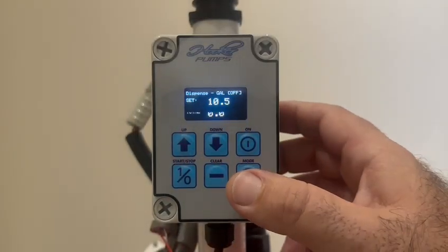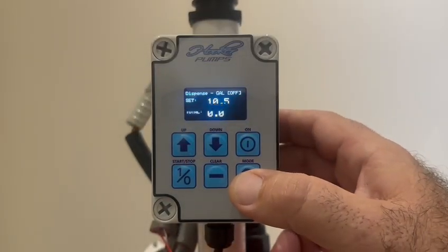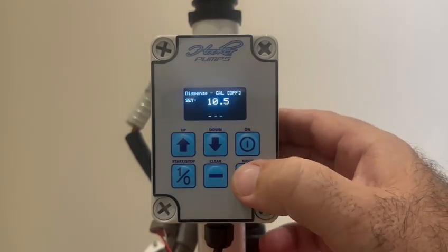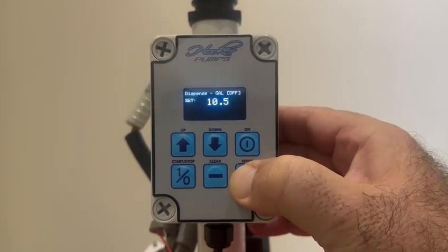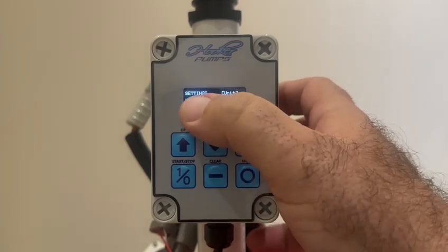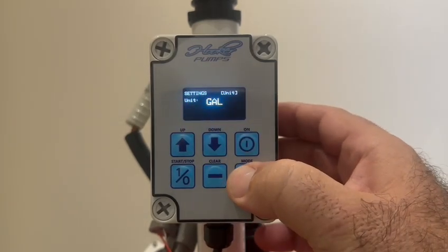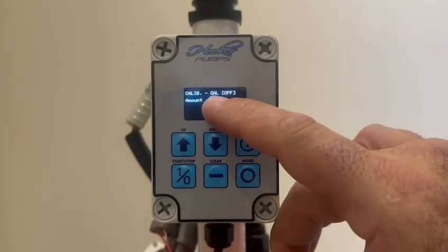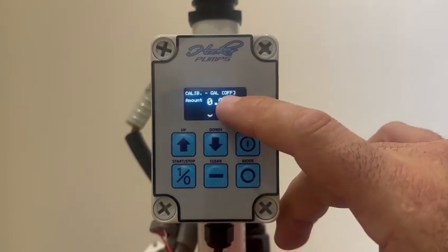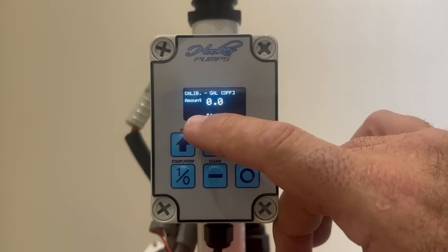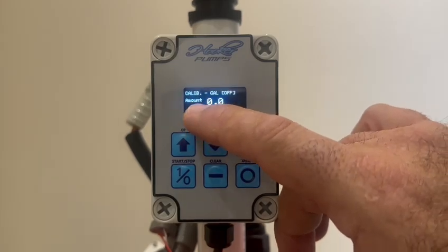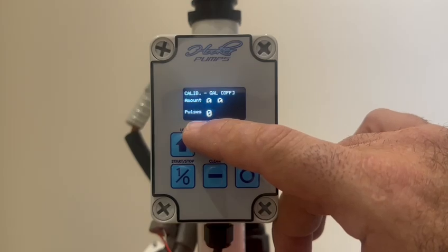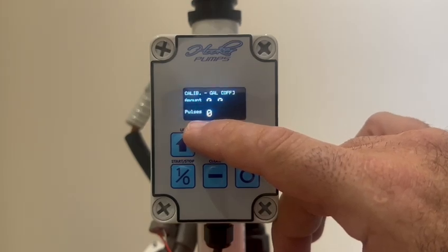Calibration. In order to adjust the calibration, I would suggest starting by pressing the on button to restart the system, and then press and hold the mode button. You'll get into the settings mode, and you're going to press the mode button again. Here you're in the calibration, and you're in gallons, and the pump status is off. What you want to do is pay attention to the pulses, not necessarily the amount in this situation, because you want a 5-gallon pail, we'll say, that's calibrated, and you know where the line is in that bucket.